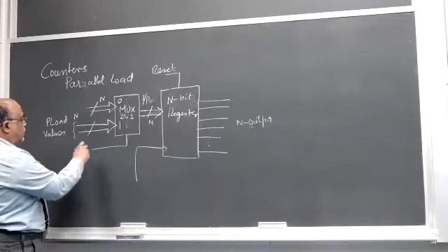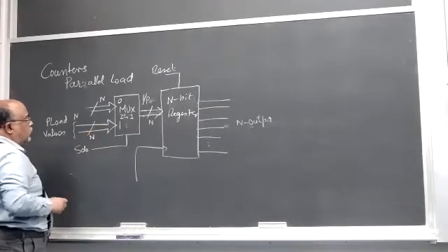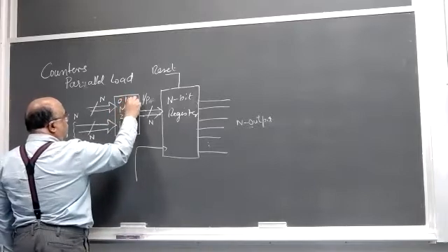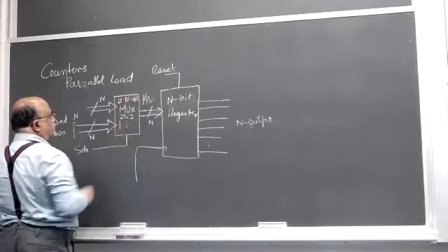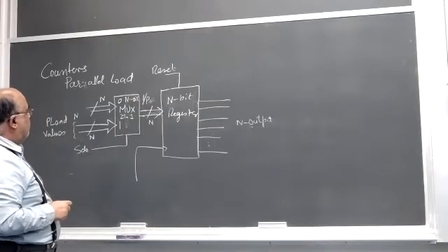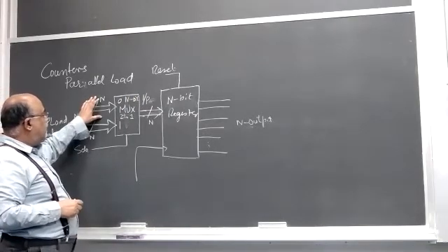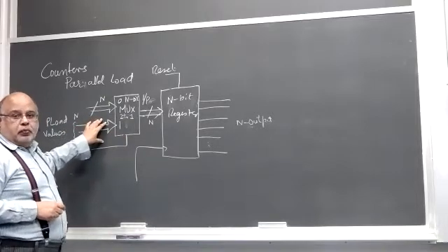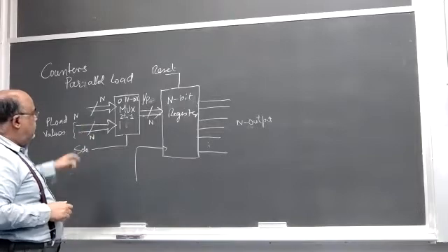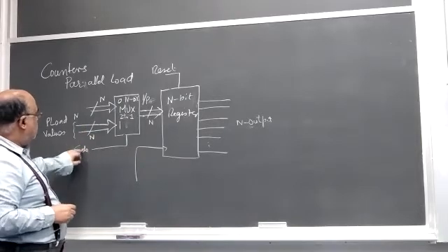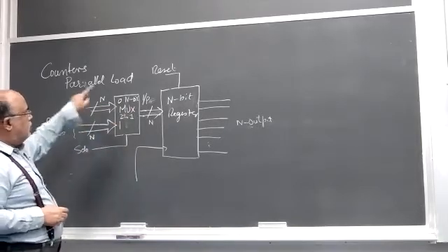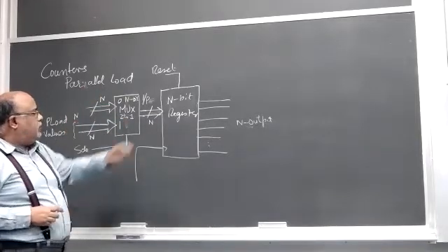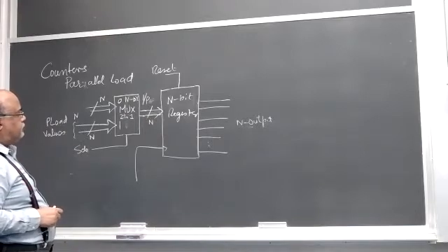So you can see here, this is a 2 to 1 multiplexer, basically an n-bit 2 to 1 multiplexer. Either these n values can be selected to become the output, or these n values can be selected. If it is 0, it will go through the normal mode, but when it is 1, the parallel load will be loaded into this.